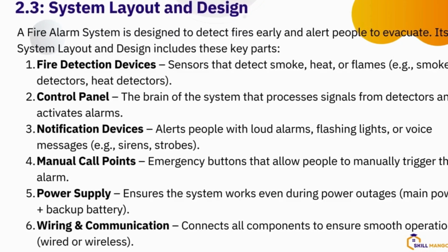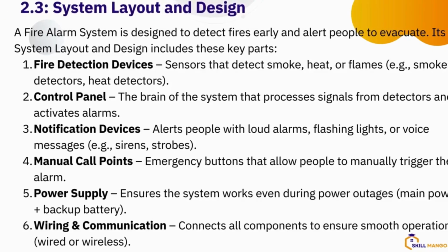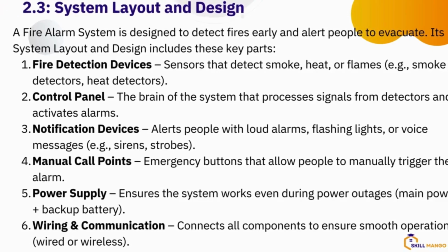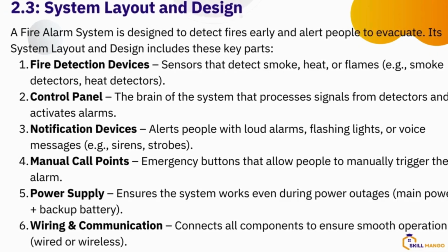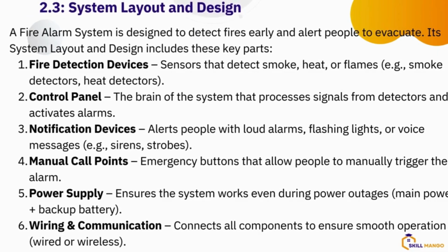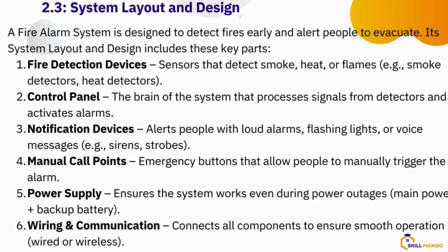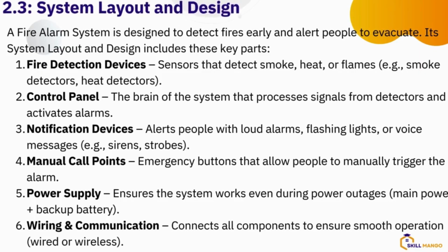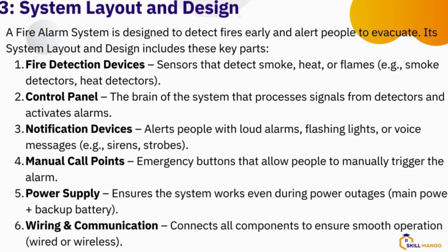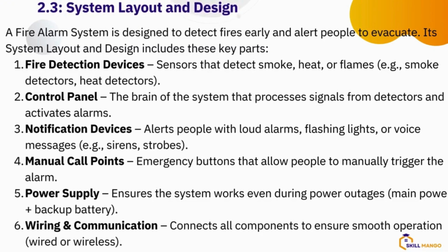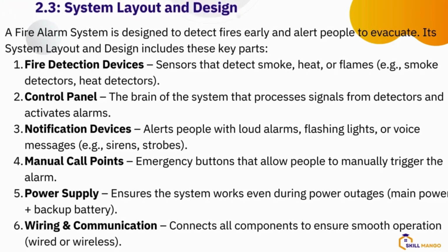All right. Then you also have to make sure you put muster point signs where everybody can assemble. And also, endeavor to make available a fire extinguisher, then train them on how to activate the extinguisher. If it's a sensitive environment, you can work a fire hose, maybe just connect it to the existing water facility in the building. So when there's a fire outbreak, you can roll the hose to the point to quench the fire.